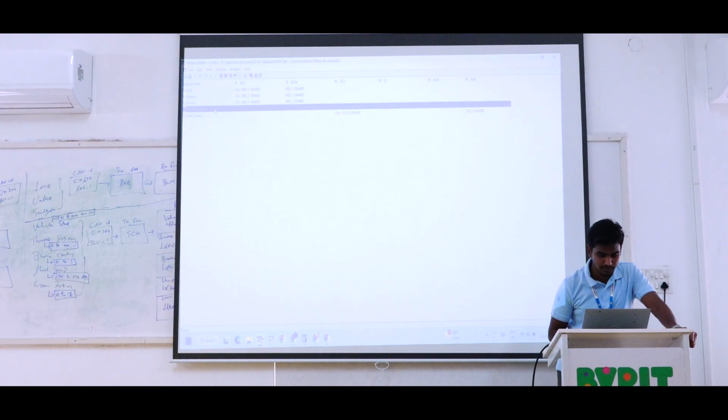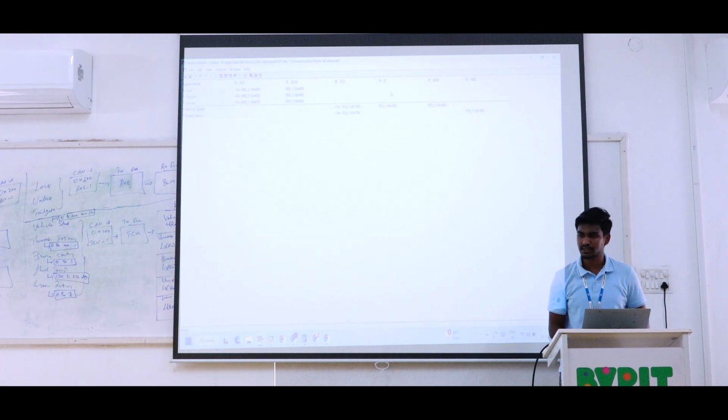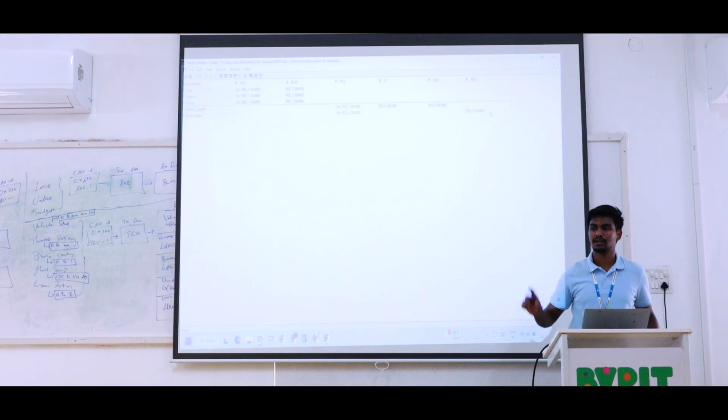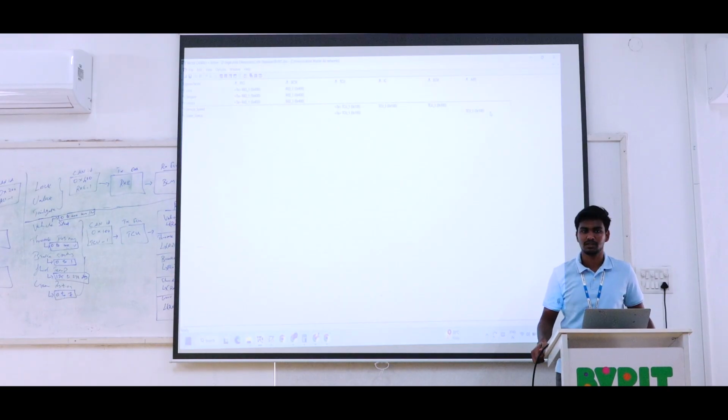But the vehicle speed is transmitted by the transmission control unit and received by the instrument cluster and the ECM. The brake status is also transmitted by the transmission control unit, but it is received by another ECU, the ABS. So these are different kinds of receivers. That is what we mentioned in the flow chart in the initial class, in the introduction slide, where signals can be received by all the receivers.